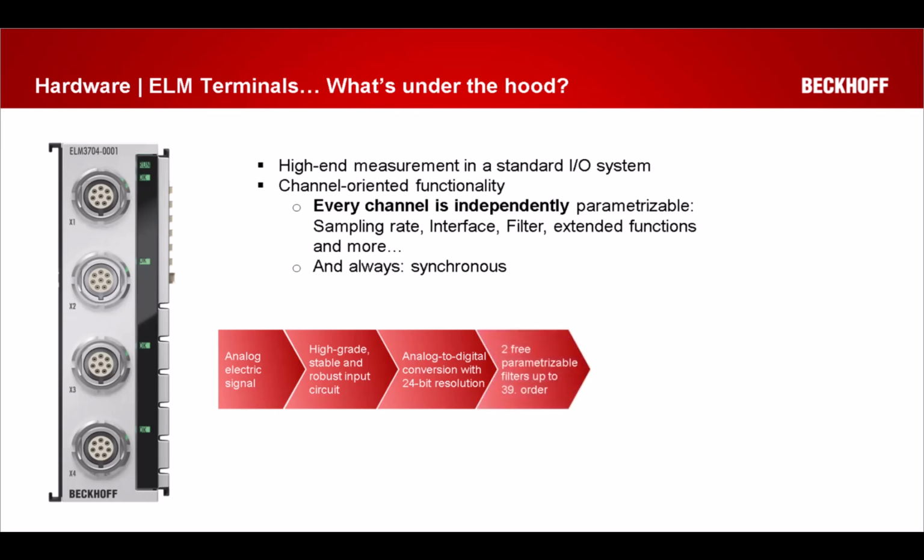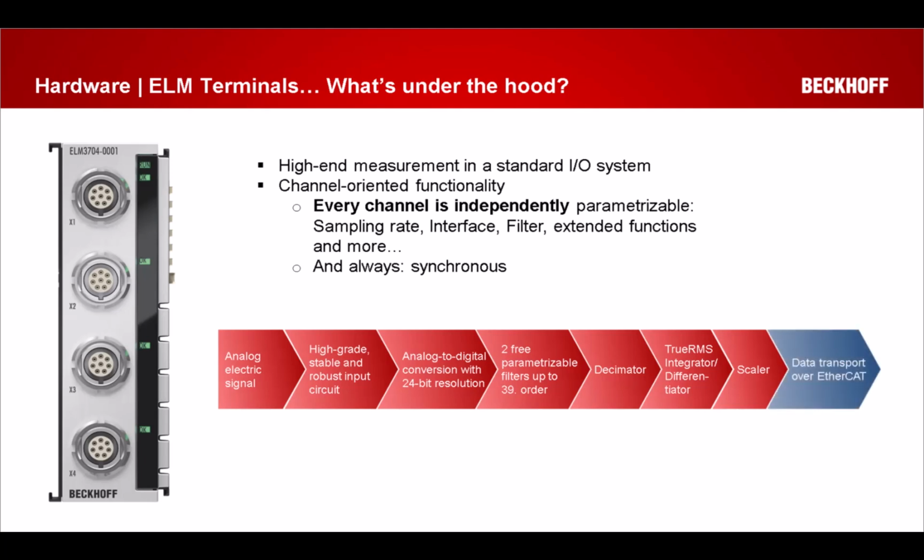And finally, we're able to take that digitized signal and run it through onboard filter stages, decimation or downsampling to get the most efficient packaging of the measurement data to be expressed over our field bus, which is EtherCAT. And additional functionalities under the hood like free scaling, tare functionalities, zero offsetting, and more.